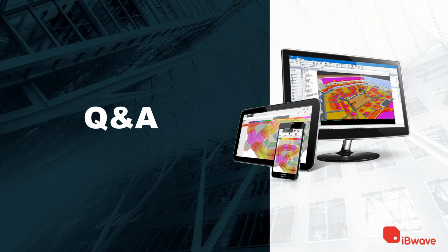In CBRS, this is different. The channels are assigned by a SAS, and you're using those channels, and you kind of know in advance that if somebody else is using a CBRS design, he will be assigned other channels unless he has higher priority. Then the SAS will request your small cell to move to a different channel. If, let's say, the military is transmitting on the channels you're already using, then the SAS will ask the small cell to move to other channels if they are available. If not, it will ask the small cell to stop transmitting or to reduce the power for the time that the military is transmitting. This is one difference.